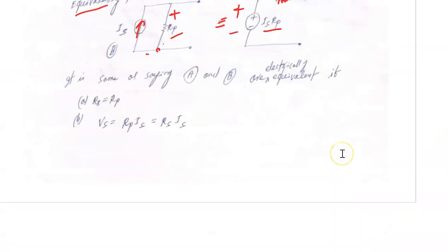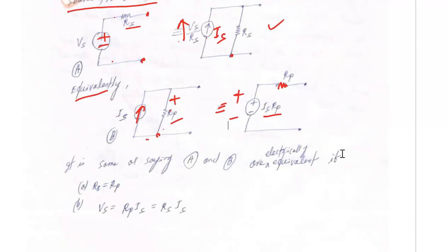Always remember, when there is a dependent source, if the dependent current value is here, and you transform this to a current source, then the dependent source will give an error, because now this resistor has been transformed, so it will not give the correct result. So this is only one point. Whenever a dependent source is there, be careful, don't apply source transformation to that voltage source.